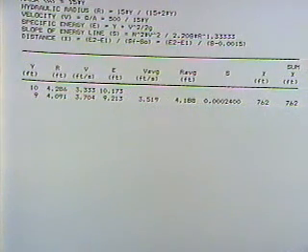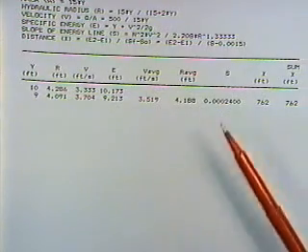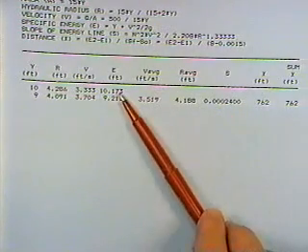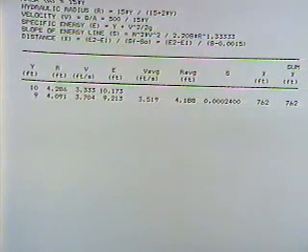You can go back in your notes. We're just a page or so back. We've got Manning's equation written in terms of an S. We solve for S. And so we know the S, we know the specific energy upstream and downstream. We plug into our energy equation to get the X, the distance between those two sections. And then I keep a column to accumulate the X. Having done it, we can do it all over again.